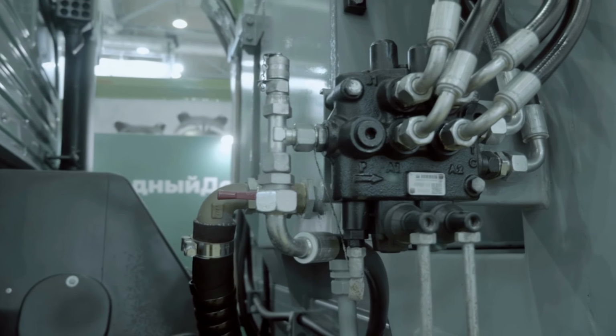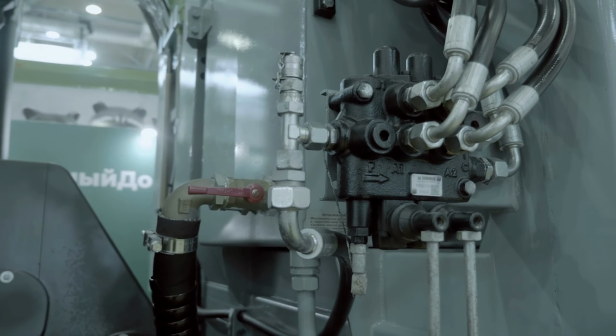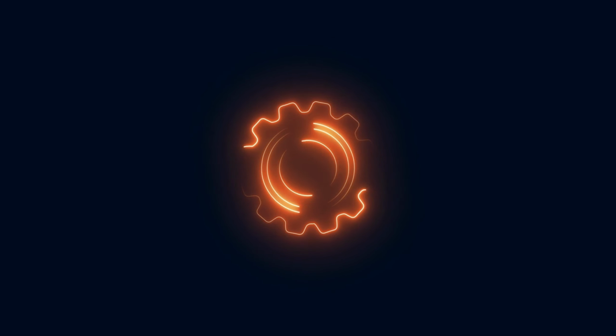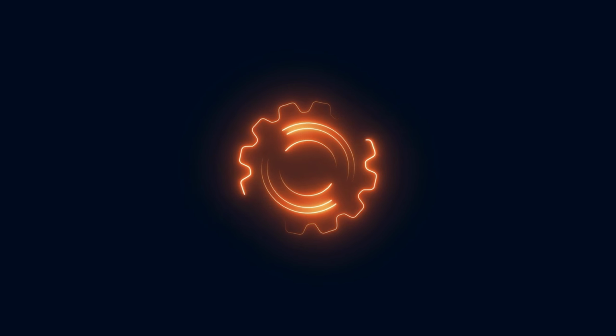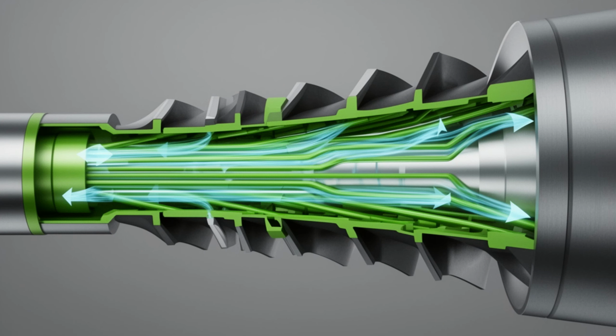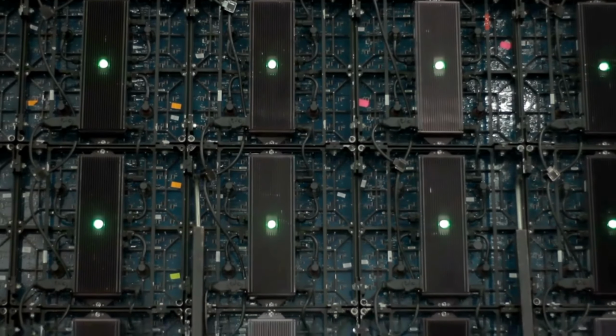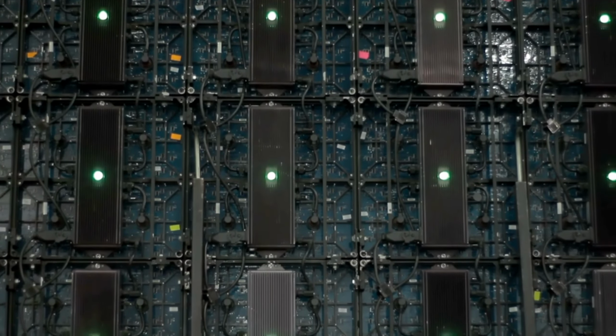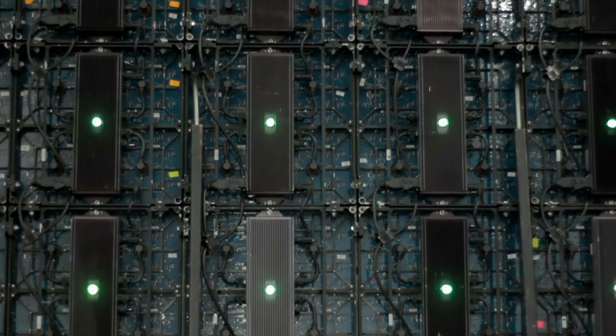Cooling and temperature control are critical throughout the process. Turbine components operate in extreme thermal environments, often hotter than the melting point of the metal itself. To survive, turbine blades are made from advanced superalloys and cooled internally using air bled from the compressor. Precise fuel control systems regulate combustion temperature to protect components and maintain long service life.